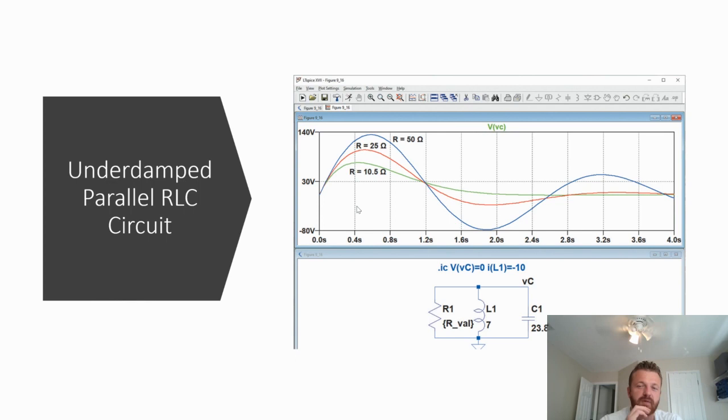So I just wanted to show you, before we worked an example, how underdamped circuits' actual responses can vary substantially depending upon the actual value of the resistance, basically how underdamped they are. If you go through and look at those actual formulas, one of the things that may be confusing is that, since you think about resistance as being the mechanism that takes energy out of the circuit or actually damps it, as R increases you would think it would become more and more damped.